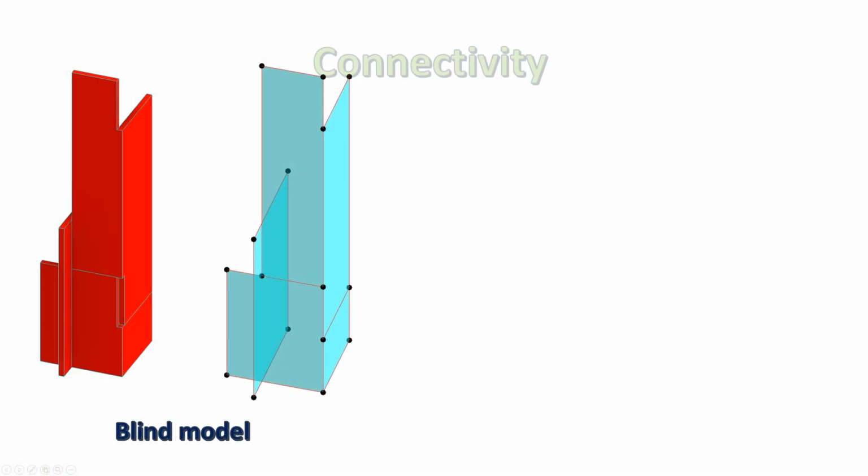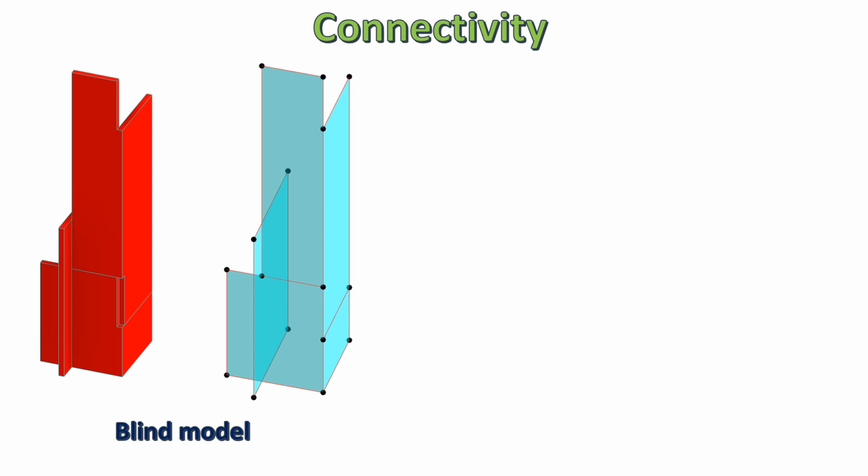Whenever there are several wall panels connected together, it is necessary to review the connectivity quality and make necessary modifications in order to make sure that both visual and structural behavior work as intended. This example shows the issue at the corner where two wall panels with different base or top constraints are connected to each other.